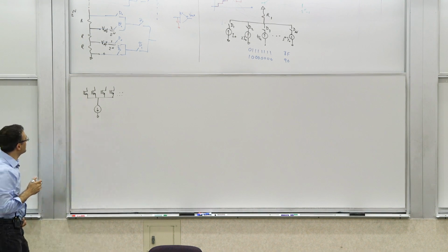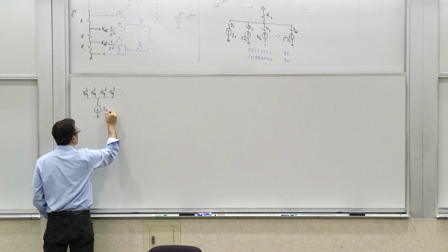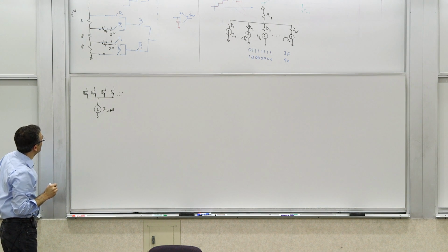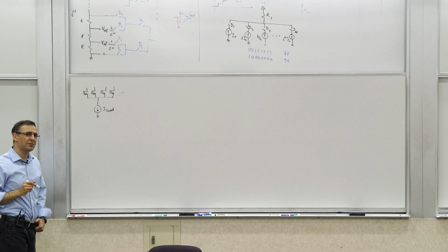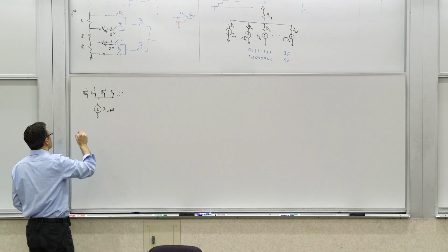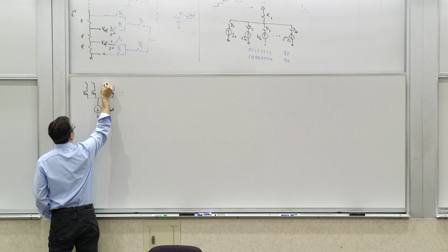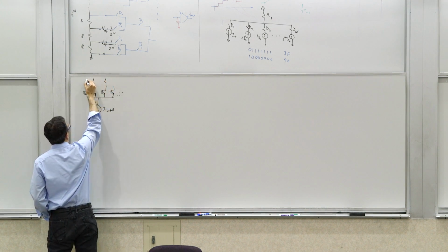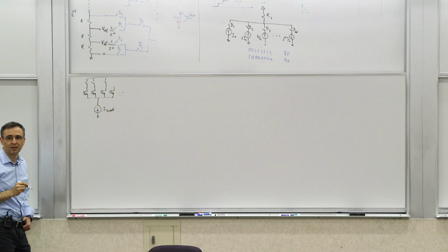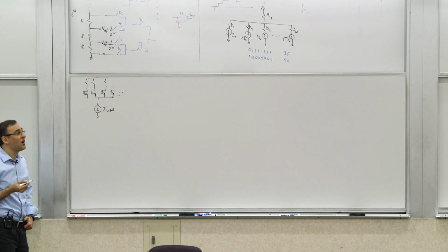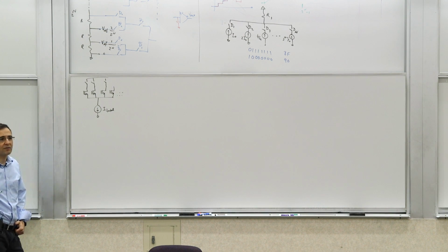Now, so let's say you have one I total. So let's say this is if you wanted to do a thermometer code example. You have a bunch of current sources like this. Can we use it, by the way we described it? So can we just have a switch now here, and then connect them to whatever? No, why not? What happens if I just do that? You always need to get I total first. Right. So it means that when the ones that you turned off, their current will end up in the other ones, right? So your currents will be unstable.